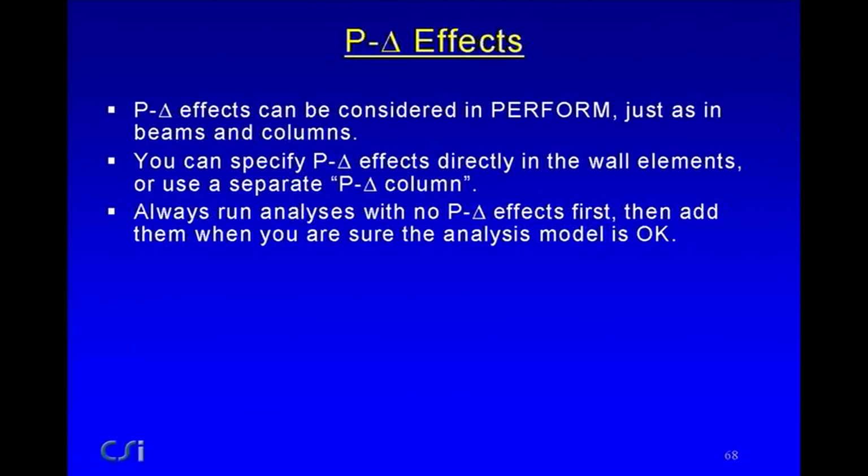And I do always recommend that if you're running an analysis with P-delta effects, then turn the P-delta effects off first, run your model, make sure it's working okay, and then after you're sure it's working okay, turn on the P-delta effects. Because I've seen often people just do everything. The first analysis people will run will be a dynamic analysis with strength loss and P-delta effects, and then they'll wonder why it didn't run the first time. Start off without any P-delta effects, run a static analysis, and also suppress the strength loss. And Perform allows you to do this rather easily. You can turn on and off P-delta effects easily, and you can also suppress the strength loss temporarily if you want to with very little effort.